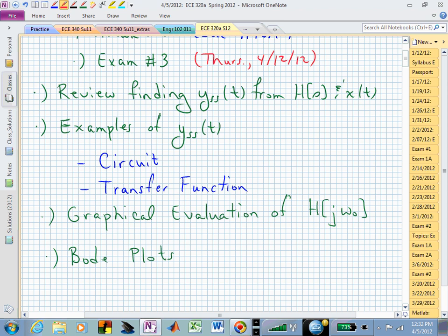Maybe they're at -2, -5, -7, etc., beyond to the left of -7 to complete the 6 real poles, and you excite your system with a sinusoid. Which pole do you examine? The one closest to the origin. That's the slowest pole, and that has the largest time constant, and you would then look at 5 of those time constants. Is that clear?